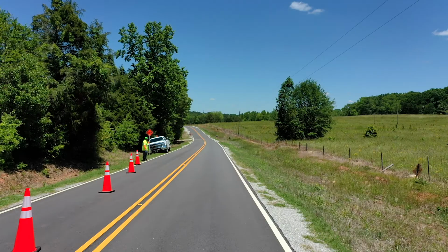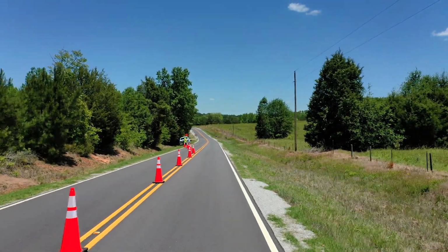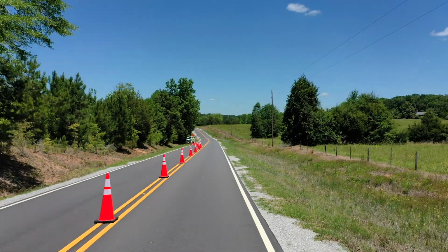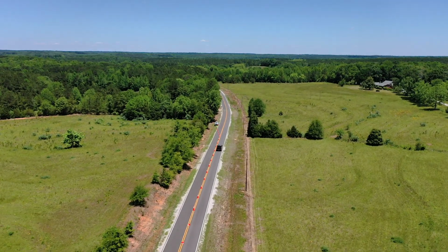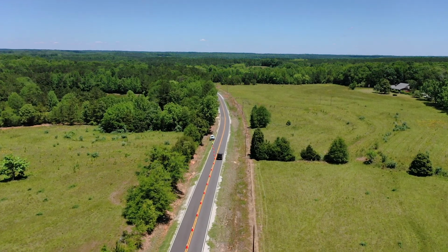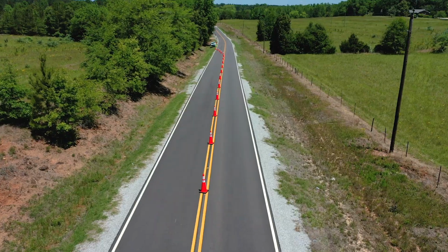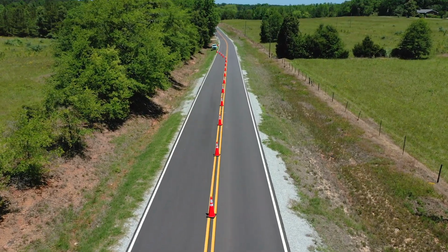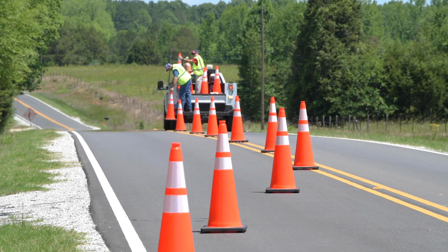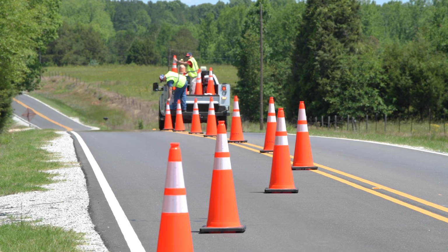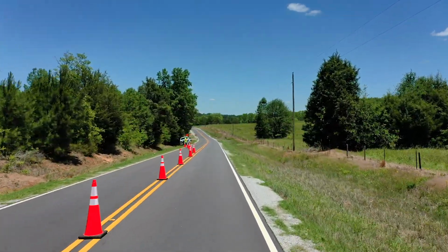Traffic then enters the transition area, where they are redirected out of their normal path into the temporary traffic space. The taper used in this application is a 1-lane, 2-way traffic taper, 50 to 100 feet in length. After passing through the transition, traffic enters the activity area beginning with a buffer space. The buffer space must be free of work. That means no workers, material, nor equipment should be within the buffer space. Finally, users encounter the termination area, where road users are safely returned to their normal path.